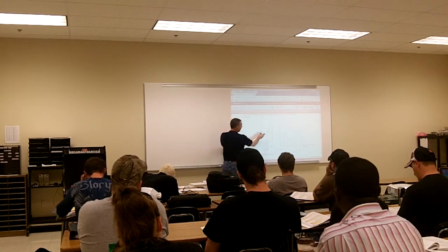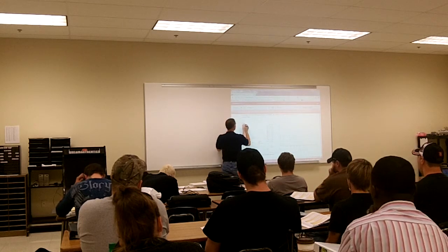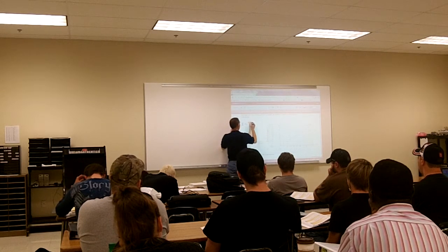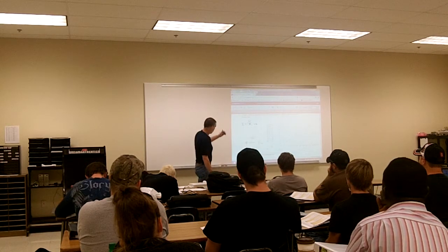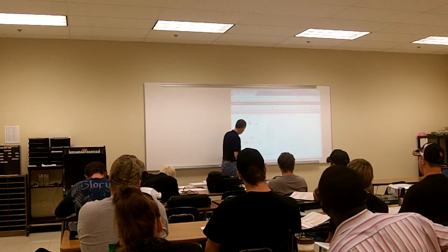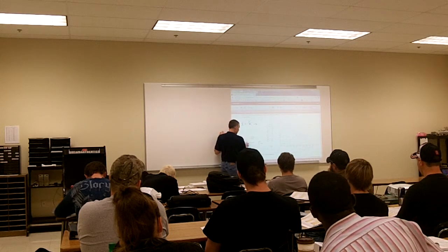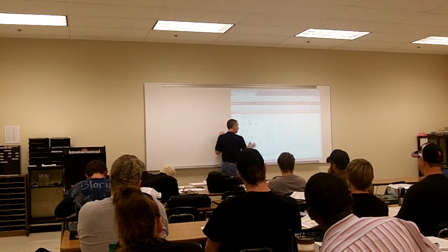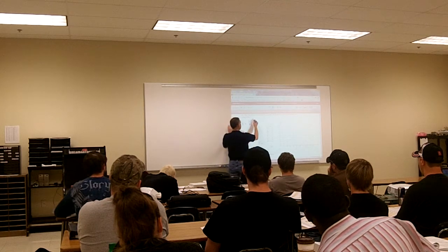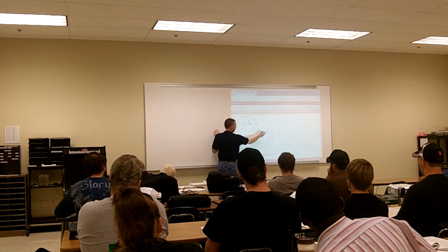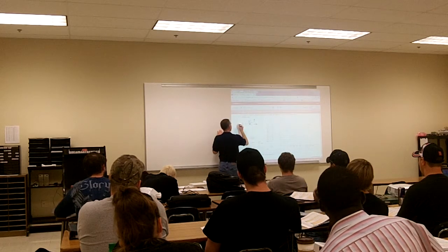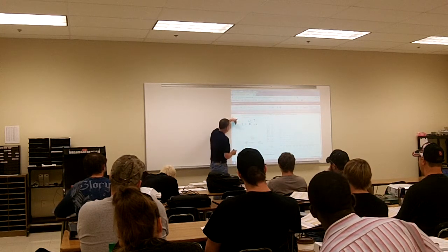because my current is equal to V over R, if my resistance stays constant, meaning at 10 ohms, and I start having a variable power supply and I start adjusting it from 10 volts to 100 volts, as I start increasing my voltage, my current in my circuit is going to go up proportionally by the same amount.